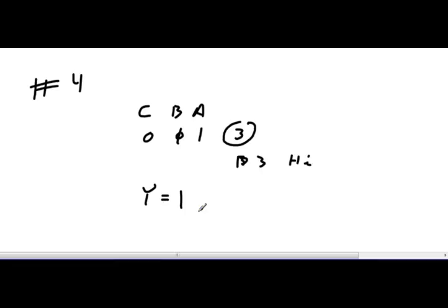I look at it, it's a multiplexer. Somewhere on the multiplexer has to be lines that are selecting which one I select. Where are they? They're at A, B, and C. Can they be any place other than A, B, and C? No, they can't be. Who's the most significant guy, A, B, or C?